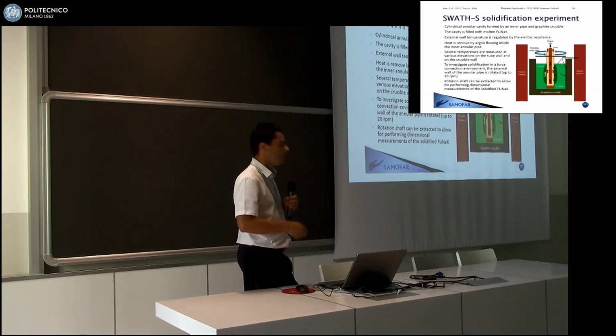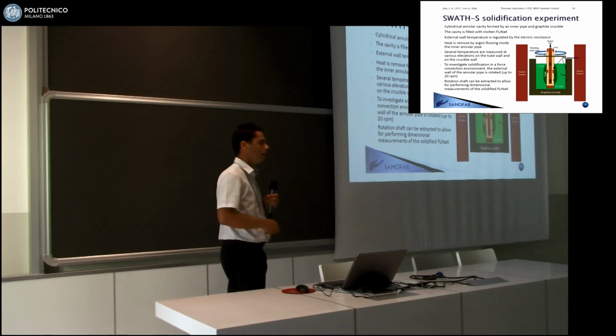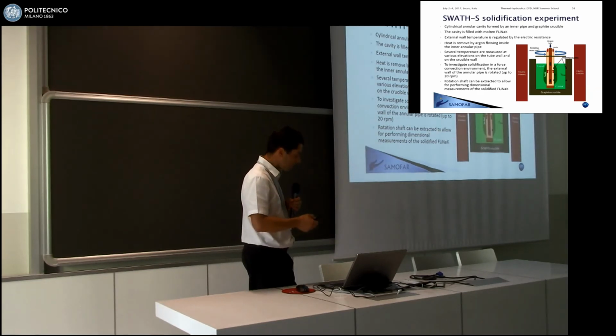Okay, so that will decrease the temperature and will induce a solidification of the salt over the surface. So the idea here is to study how solidification progresses, let's say, without any convection or very little natural convection. And then the nice thing is that this cooler can rotate about itself, and then we can study solidification under a convective velocity field.